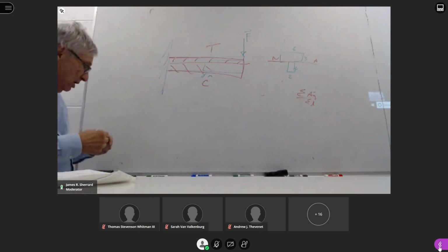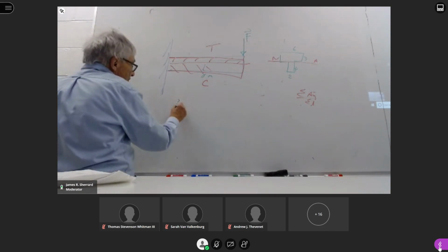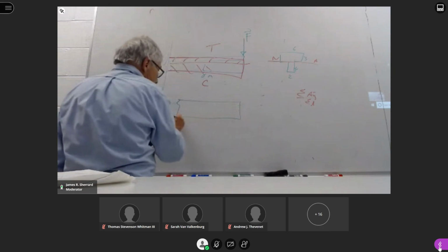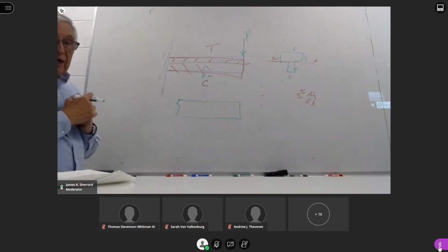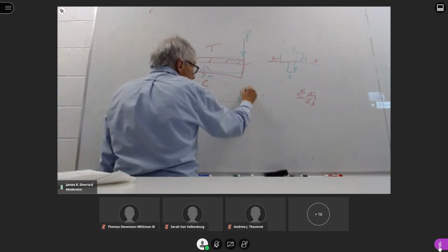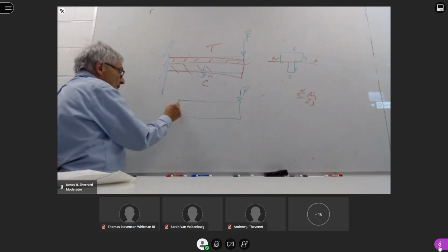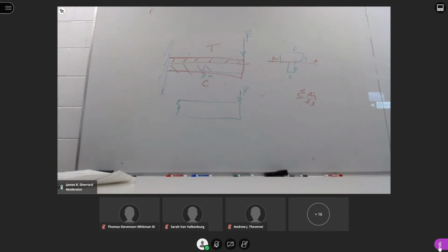But to really see what goes on, we're going to step back a couple weeks and do a complete free body diagram. So if I sketch the member, drawing any given forces, moments, torques, couples, the one I have is the force at the end. How many attachment points do I have? I have 1. So we know we can only add forces, moments, torques, couples at our attachment point. We're going to have to use the 6 equilibrium equations to see what's going on.